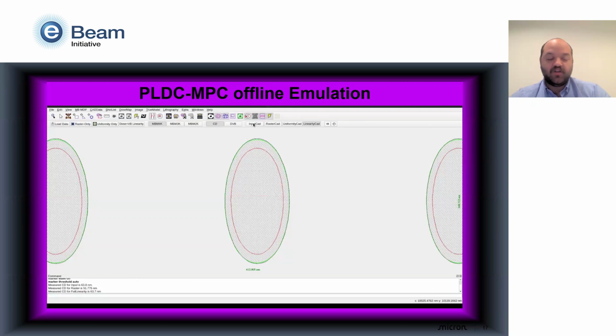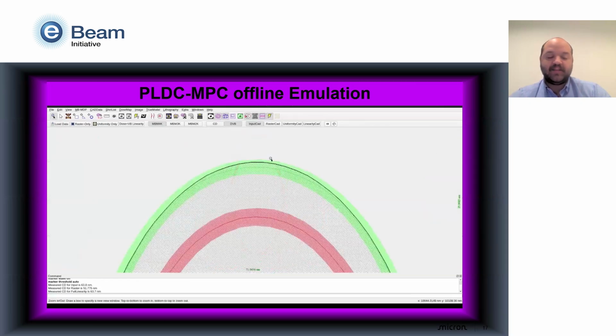So we're going to turn the dose variability band on, and we're going to zoom in to the tip of this feature. The dose variability band is essentially the plus or minus 10% dose for a given feature. You can draw the same sort of cut line through the tip of this, and you can see what plus or minus 10% dose variability would be.